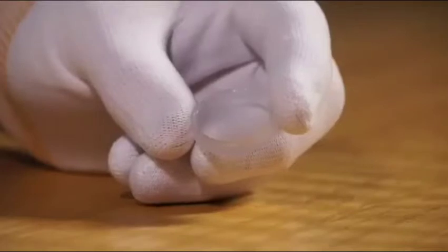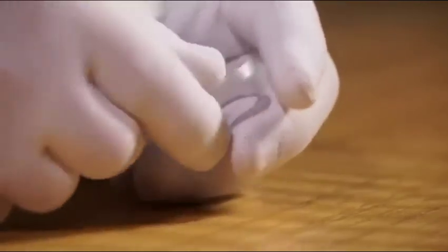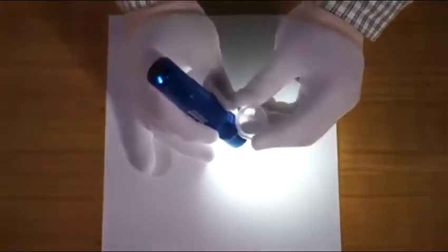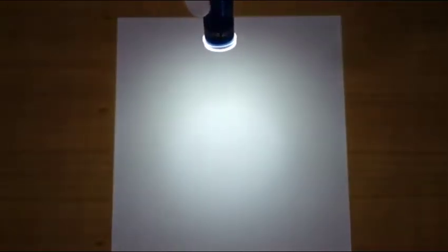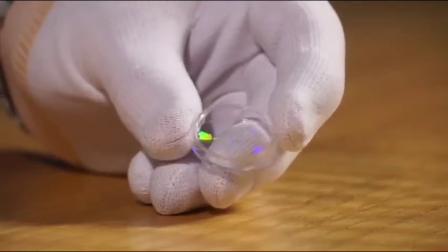The next end cap reproduces a chemically etched square grid of diffusion type structures. This chemical etching process produces a surface with a diffusion of light similar to the bead blasted surface. The surface structures are about 75 microns deep. Note that this type of structure, and a myriad of others, could also be created using a laser engraving process on the mold tool. The last cap features a more intricate surface.